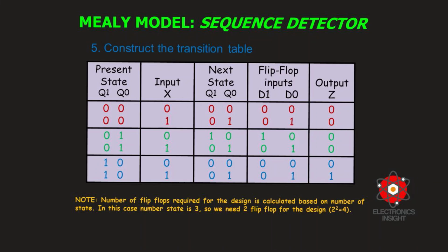output. Because it is a state transition table. It's not your excitation table. In the state transition table, you will fill the flip-flop inputs from the next state output. You will have to check your excitation table also so that you know what output you have got. Based on that, you will fix your flip-flop inputs. Since it is a delay flip-flop, whatever was there in the input only would have propagated to your output. So the same thing we are trying to fill up.